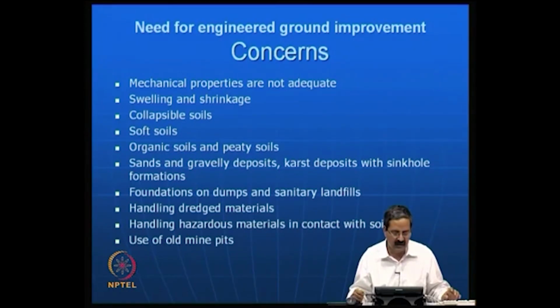And organic soils are another component in soil mechanics, where certain materials have a lot of organic matter in them, and because of the poor drainage conditions, organic soils are also quite tricky, like marshy areas, which are standard in many places. When we treat the soils in some form, these soils become usable, like one can construct roads or buildings on them. This is only possible by means of ground improvement techniques.